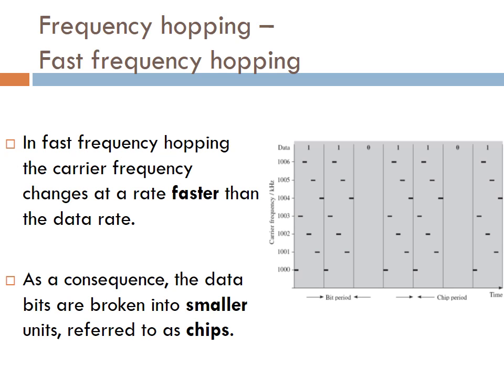As with slow frequency hopping, the hopping sequence is predetermined and known by both the transmitter and the receiver. Once again, signal detection can be done by the receiver correlating against the hopping pattern. The advantages of slow frequency hopping, security from eavesdroppers and tolerance to bad frequencies in the channel, are also found with fast frequency hopping.